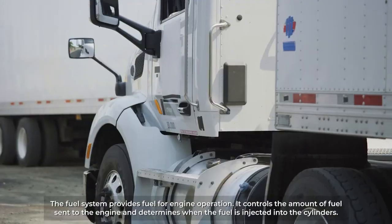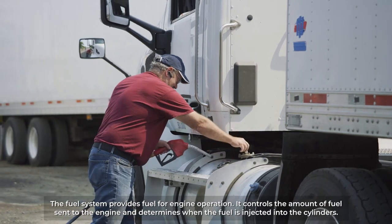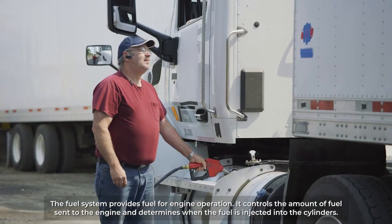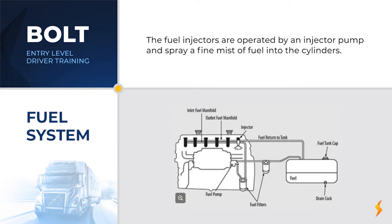The fuel system provides fuel for engine operation. It controls the amount of fuel sent to the engine and determines when the fuel is injected into the cylinders. The fuel pump draws fuel from the fuel tanks through the fuel lines and fuel filters to the fuel injectors. The fuel injectors are operated by an injector pump and spray a fine mist of fuel into the engine cylinders.